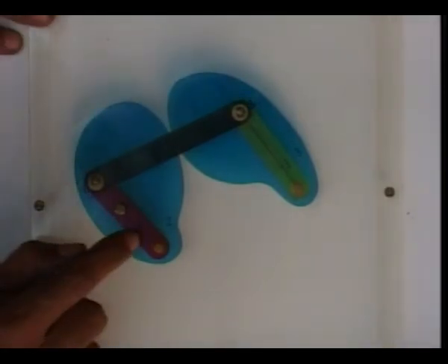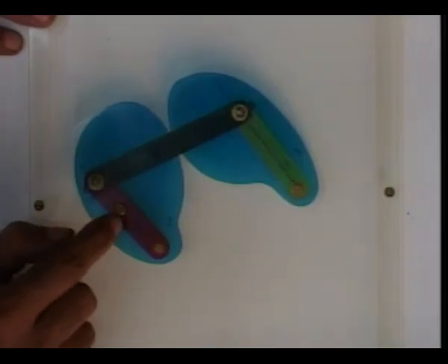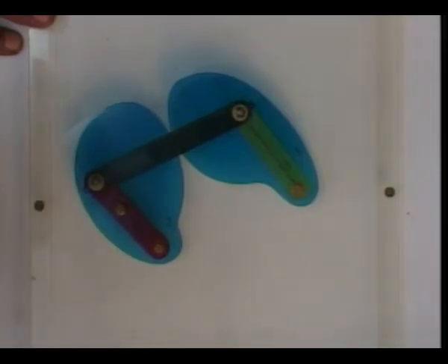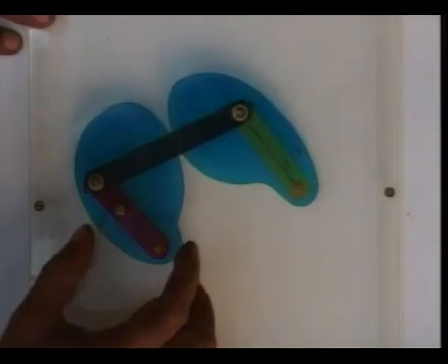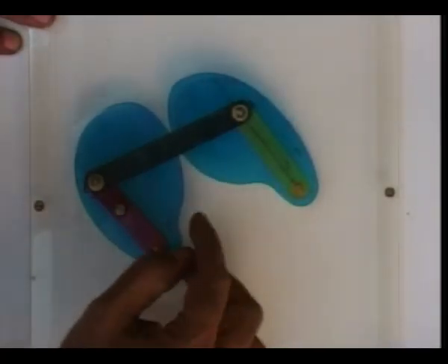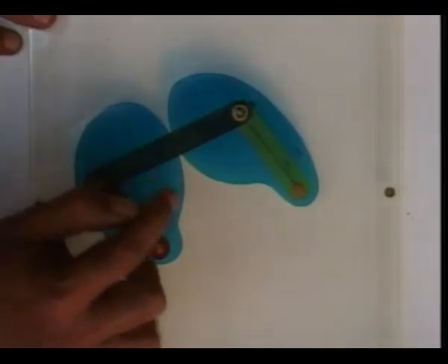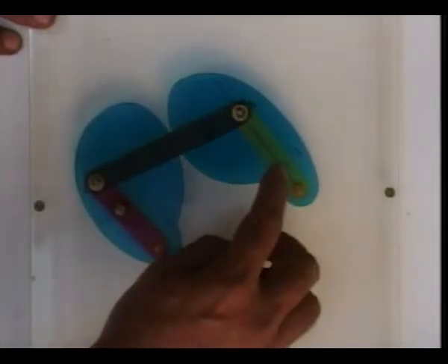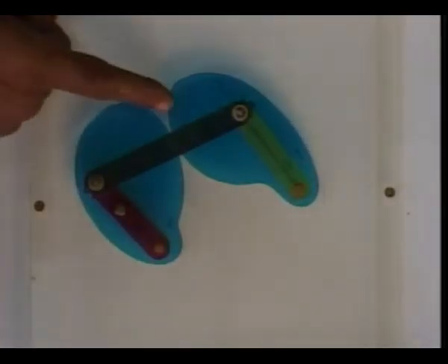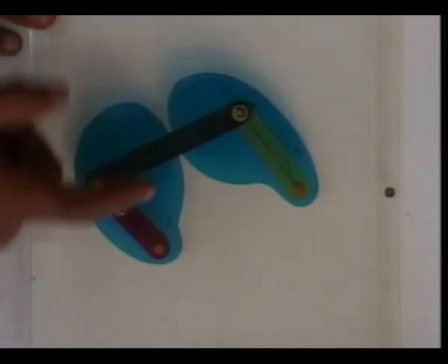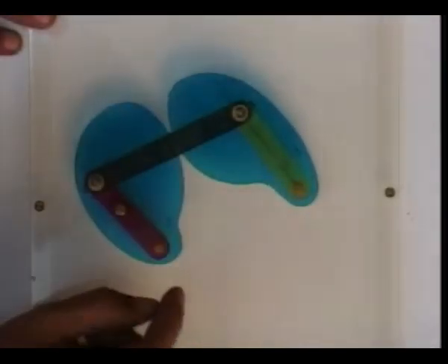I have connected these two bodies, that is this red link and the original link number 2, rigidly. And as we shall see, when I move this mechanism, the same motion is transmitted at least around this contact region between body 2 and body 3, whether it is through the higher pair mechanism or through this equivalent lower pair linkage.